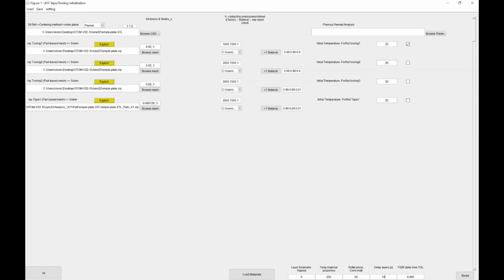And this is the delta time that the solver will use. A lower delta time will guarantee the convergence, but it takes more steps to reach that convergence. So it is usually recommended that you don't change the default value, but if you don't get convergence, decrease it.